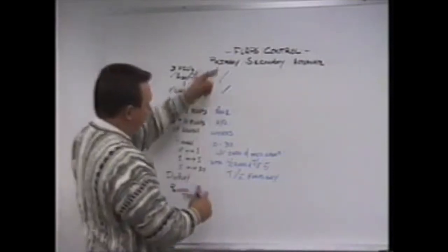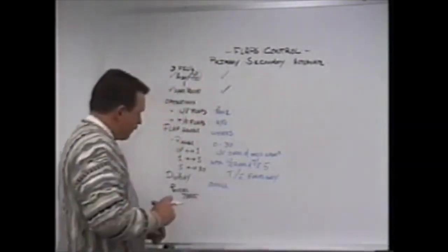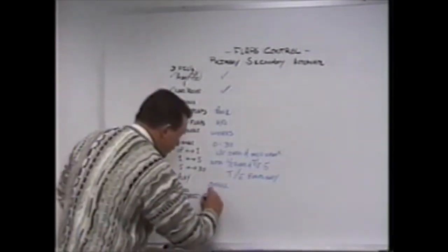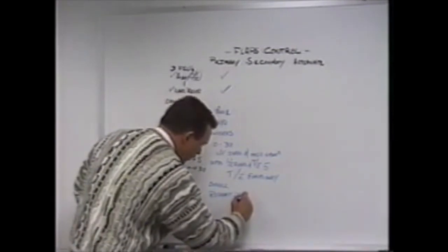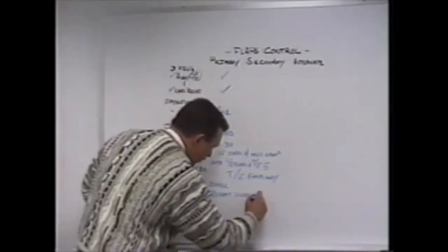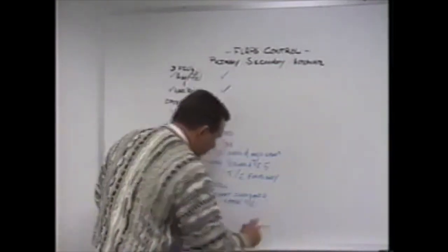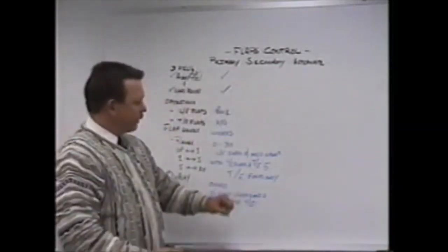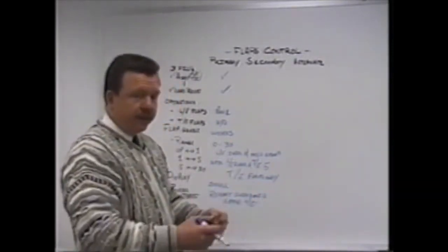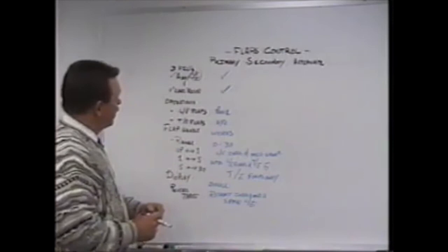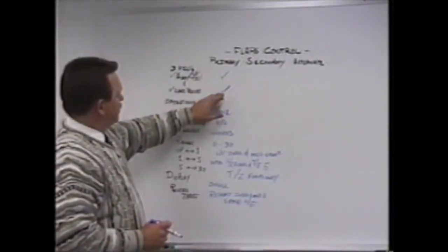Your display in the primary drive is a single vertical tape. Going into reverse thrust will retract inboard and mid-span leading edge flaps. So going into reverse thrust will automatically retract the inboard and mid-span leading edge flaps. As you come out of reverse, there's a short delay and those leading edge flaps will redeploy. So asymmetry protection, both leading and trailing edge flaps, load relief on the trailers only.